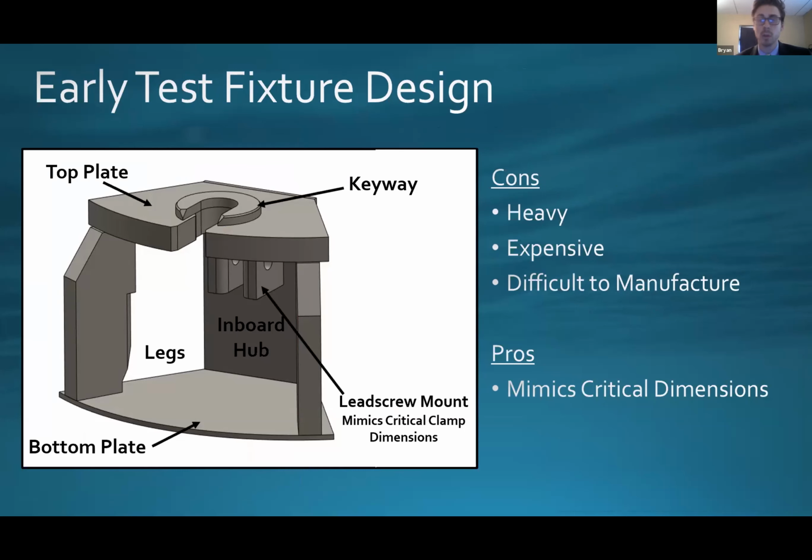We were able to keep our costs well below budget by doing all the fabrication ourselves with the guidance and help of our machine shop foreman, Neil Reinhardt, as well as our friends that work in the Proto Lab. We utilized Tech's machine shop to its fullest, employing the water jet and plasma table to cut our 1/4 inch and 1/8 inch plates. We utilized the CNC mill to fabricate our bearing housing and motor mount, as well as wood routers and the thingery to construct jigs that significantly simplified all of the welding that we had to do.